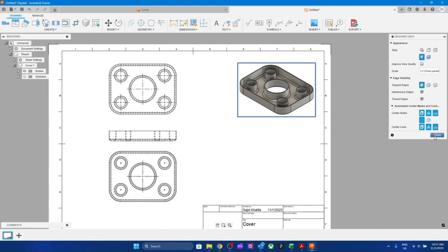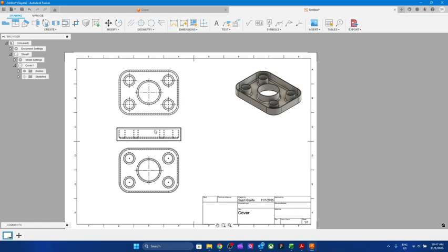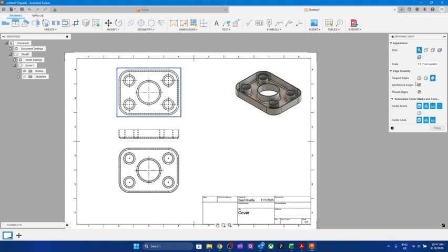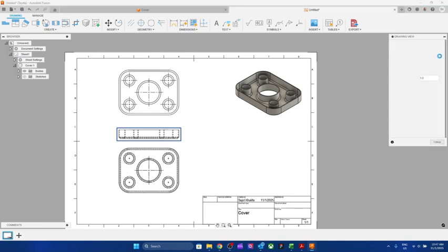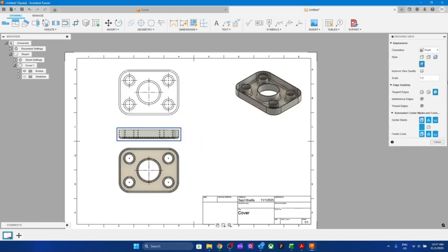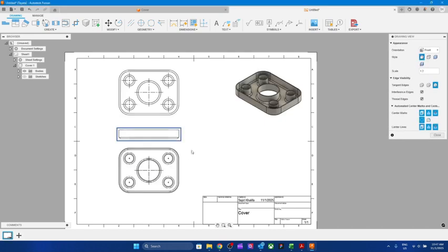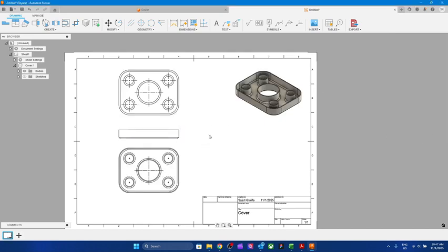So close this, you will close this, and then if you don't want to show the hidden line, double click, and let's say this is not hidden line, visible edge. Can you see it's becoming more tidy, tidier, I would say, cleaner drawing. This one, double click, and you might want to show it shaded or only this. You can see, okay. So that shows inside, that showed the back, this shows the front.